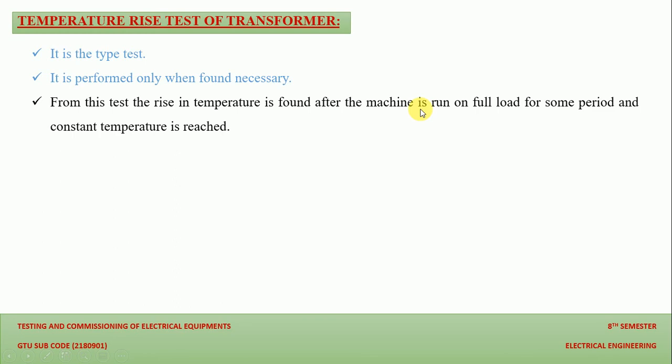As we have discussed, as we run the machine for our load, according to the change in the load, the current requirement will change, and as heavy current transfers through the winding of the transformer, the winding will get heated up, and the insulation surrounding the winding will get heated up too. As large transformers are oil immersed, the temperature of the oil will also increase. With increasing temperature, the property of the oil will deteriorate.